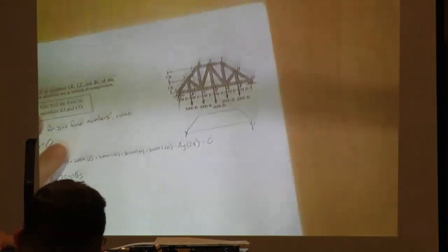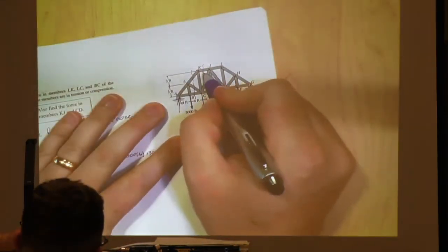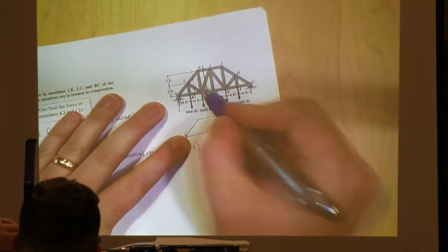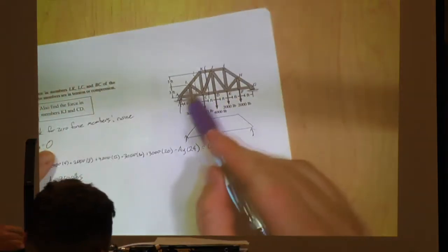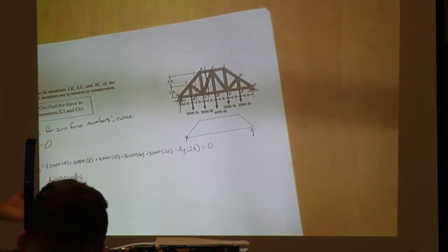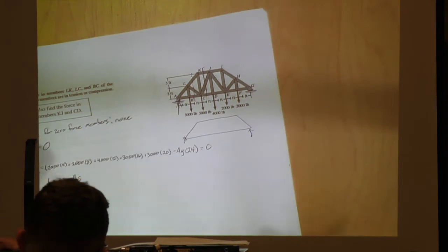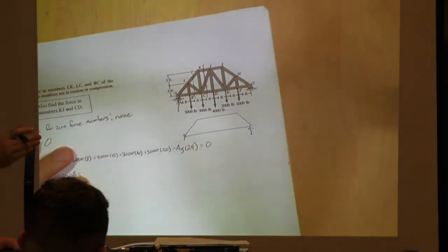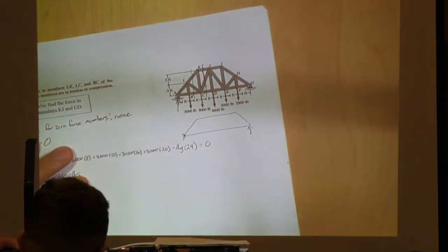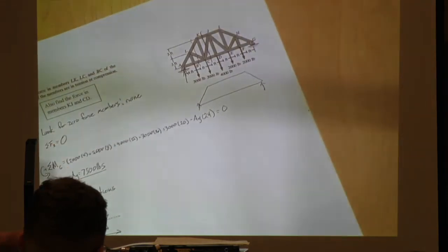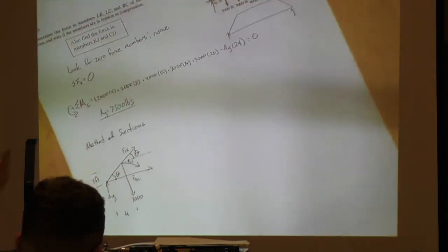So if we were up here and I cut here, what am I doing with all this? You treat it as a rigid body. This is the beauty of method of sections. You cut it, and the members that you cut only become the reactions. Everything else you treat as a rigid body, so you don't have to worry about going joint by joint and finding each one.